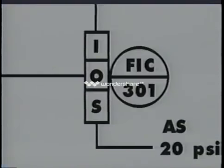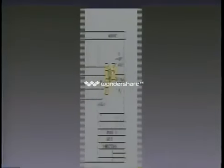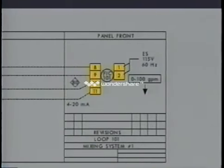The flow controller has an instrument port with three connections, labeled I, O, and S. So you know there is a port for the input signal, one for the output signal, and one for supply air. Electronic controllers have positive and negative input and output terminals and electrical supply connections. These terminal designations are determined by instrument manufacturers.